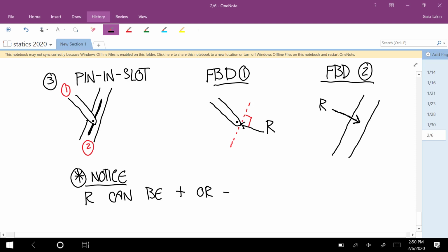Any other questions? So that's all the three types of joints in this first category that introduce one variable. This is a 2D problem, so when I say that these introduce one variable, how many total unknown variables can you solve for with Newton's laws? 3, yep. You have 3 equations, the x and y equations for Newton's second law, and the z equation for the rotational. Okay, so if you have one of these 3 types of joints, you can solve for 2 other variables along with it.